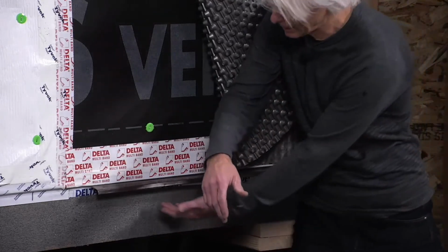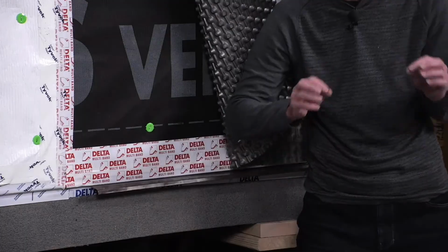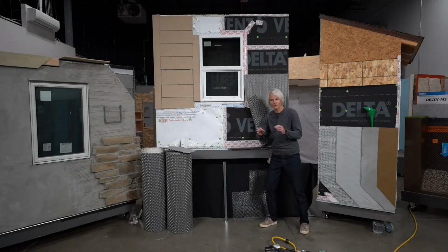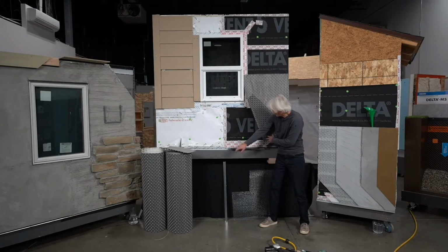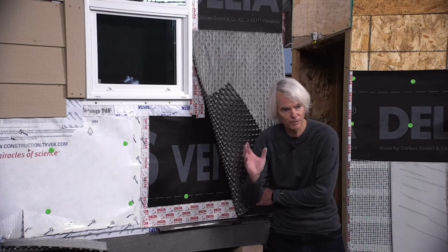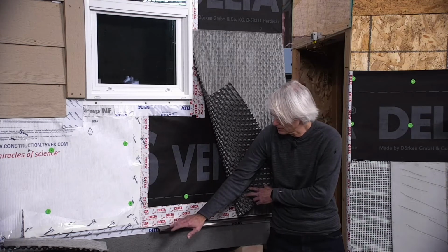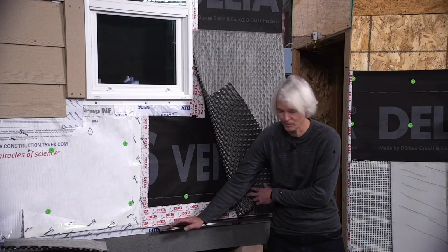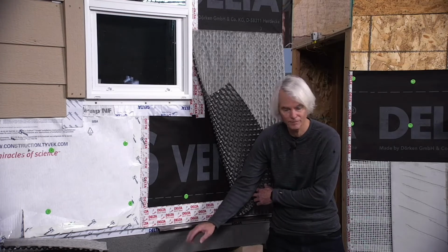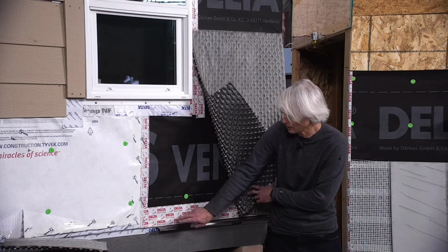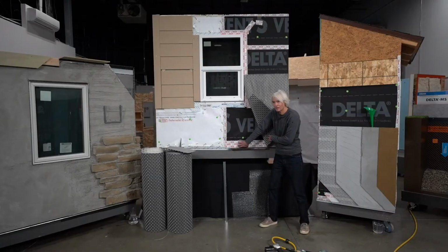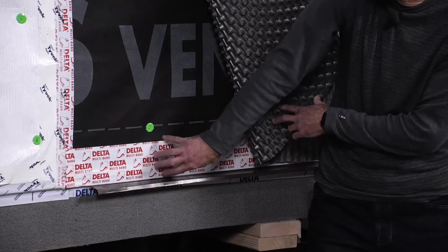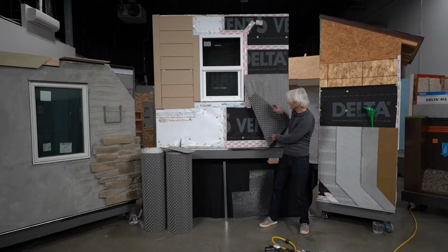And that's really to protect things from splashing up at the bottom, and also is a really good way to terminate or detail the air barrier. The next step is that we've got this metal flashing. This is not the weep screed. We're going for a Stucco assembly here. This is not the weep screed assembly. This is a piece of diverter flashing at the bottom of the wall to kick that water out and off that assembly. We'll get to the weep screed shortly. This layer of flashing is integrated up behind the weather barrier and then sealed off to maintain both some water holdout and our air barrier detail. So that's that first piece.